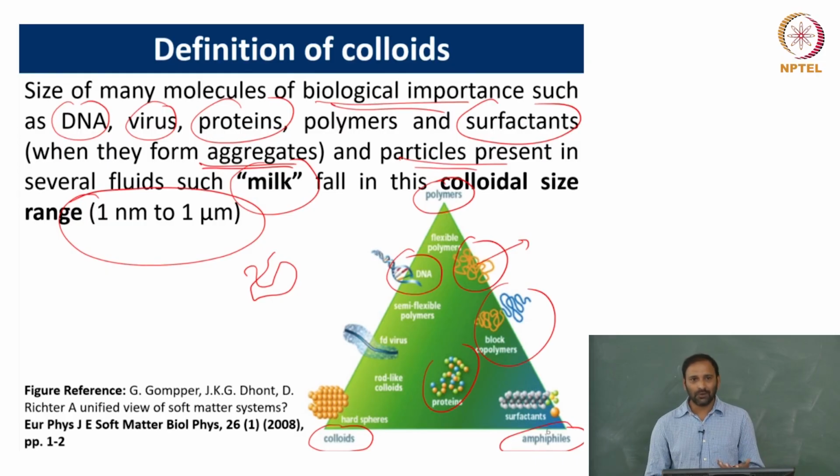But you could have a system where two polymers are connected by a covalent bond, as in the example given here. The orangish color is one type of polymer, and the blue is another type of polymer. Again, they are connected by a covalent bond. That is an example of a block polymer. You have two different polymer molecules which are joined together. That is why it is called a diblock polymer. You can have 3 different chains, called a triblock polymer, and so on and so forth.